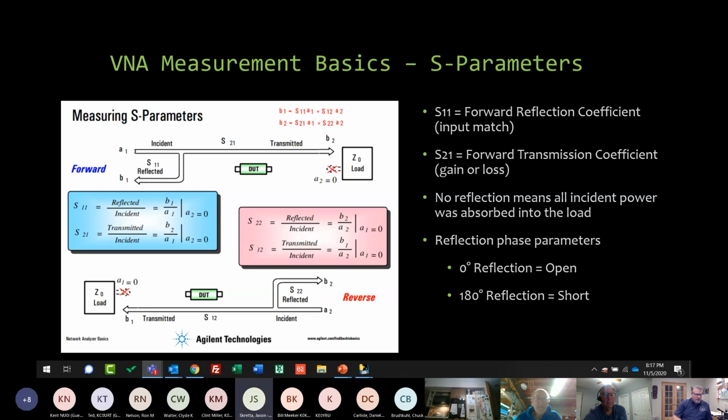No, that's right, thanks, Jason, for calling that out. You can see here the S22, S12. Really, it's the reverse side. You could feed it back through. There are some measurements where you might end up swapping cables from port to port and measuring the reverse and then measuring back. That would be a case where you might gain some from a more complex instrument. But realistically, you're looking at probably something minimum in the $2,000 range. And even then, you might not end up with a multi-port device. So good question, Bill, and thanks, Jason, for highlighting that.